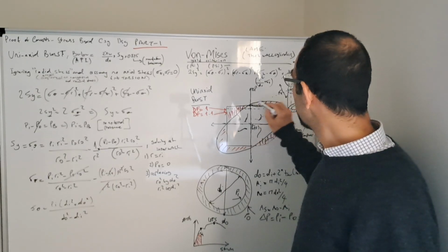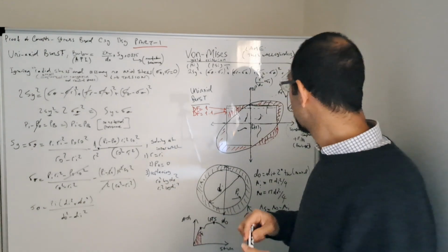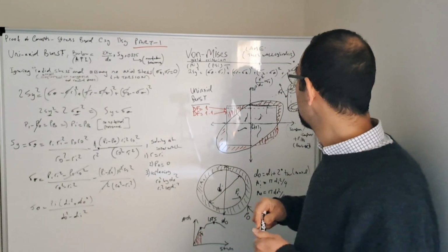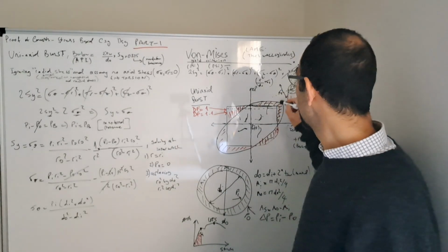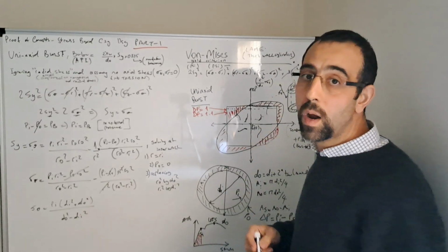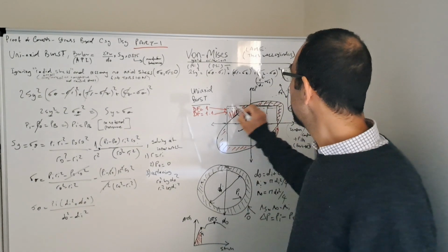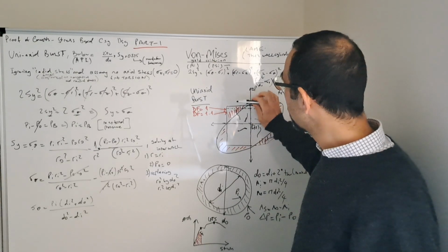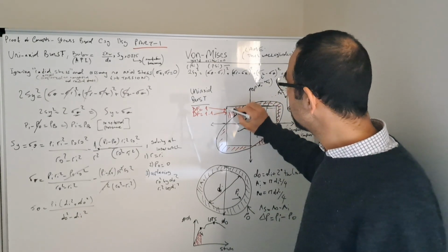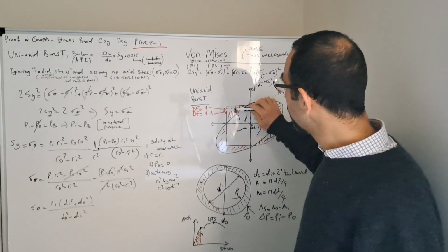However, on some sections the limits are a bit different. That's because the axial stress is being considered with the triaxial analysis and not with the Barlow or the uniaxial rating. And this one, as I mentioned, is the uniaxial rating. I set the design factor as 1 at the moment. When you increase your design factor, it will tend to go down.